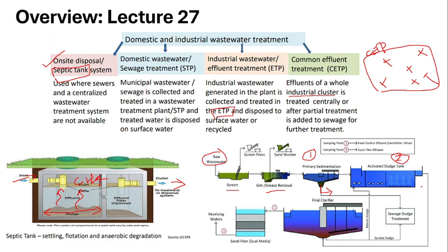And this is an aerated chamber so that all the microorganisms, in the presence of oxygen, will degrade the organic content in the wastewater, and the sludge formed is again collected. And this is the final clarifier where the sludge is again separated from the treated water, and only the pure treated water is allowed to flow through the sand filter media, and finally the purified water is received out here.